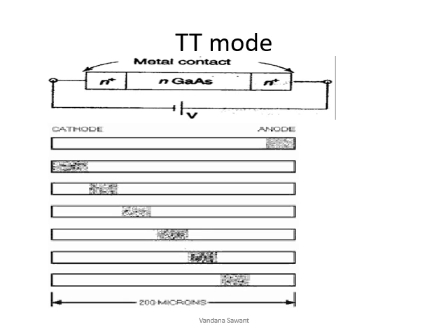So when the bunch of electrons is near the cathode, there is no output current at the anode. Now when this bunch of electrons travels towards the anode and reaches it after the transit time, suddenly a large amount of electrons are reaching the anode. So at the anode, a large amount of current will be there at the output side.